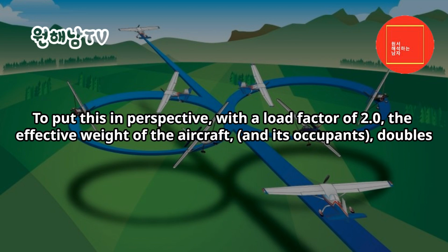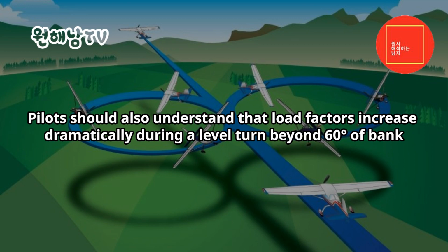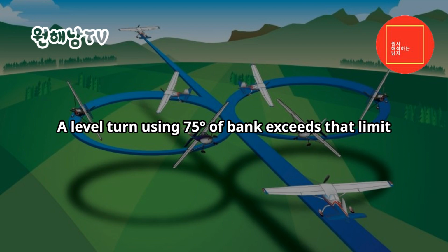To put this in perspective, with a load factor of 2.0, the effective weight of the aircraft, and its occupants, doubles. Pilots may have difficulty with orientation and movement when first experiencing these forces. Pilots should also understand that load factors increase dramatically during a level turn beyond 60 degrees of bank. Note that the design of a standard category general aviation airplane accommodates a load factor up to 3.8. A level turn using 75 degrees of bank exceeds that limit.